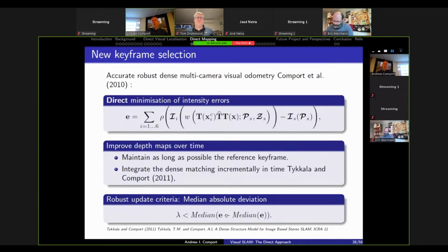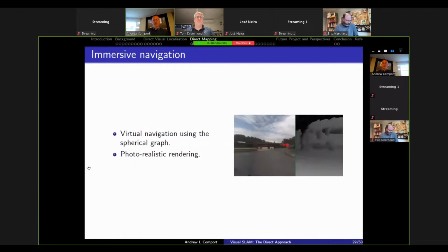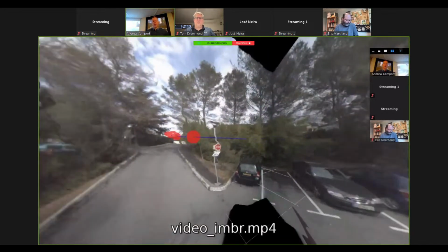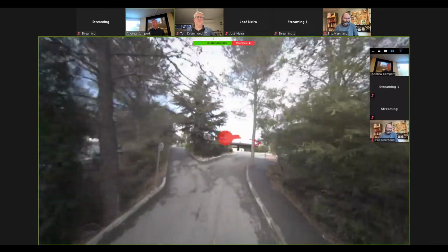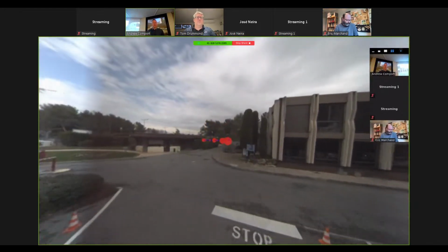And then we've worked a little bit on how to choose the keyframes, how to place them in the environment to have an optimal map from this keyframe representation. So we want to basically be looking at the statistics of the estimation and knowing where we're going to be localizing better by placing the keyframes correctly in the environment, whilst also densely covering the map of the environment. So I just have a little example here of this. This is kind of like a video game. We've performed this mapping with the spherical system, and we have the poses between the keyframes that we've estimated.